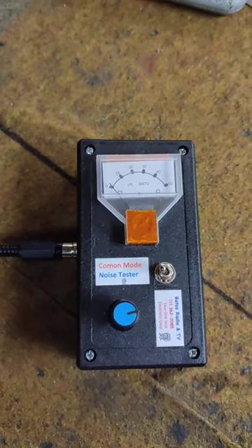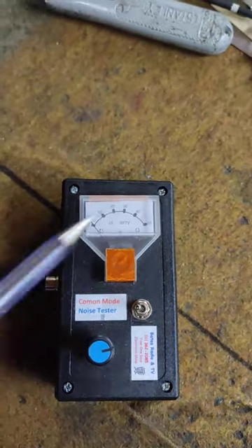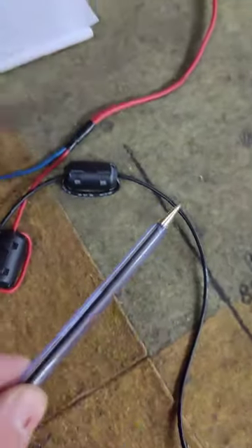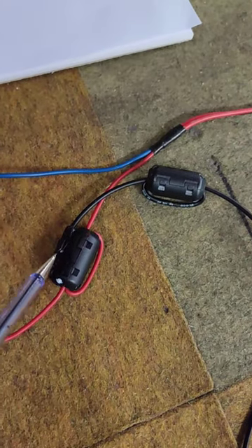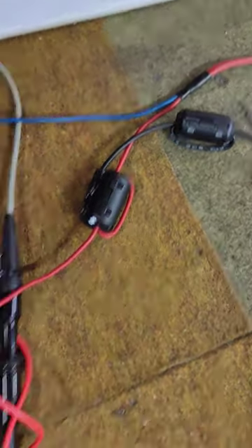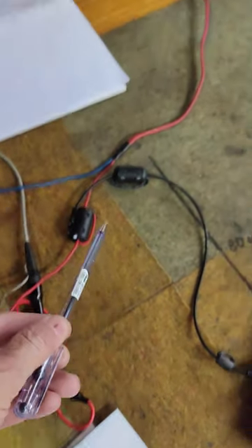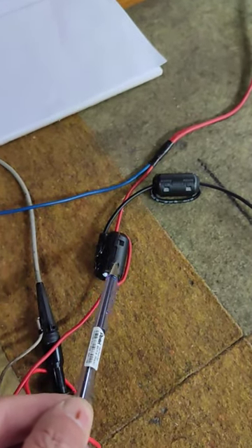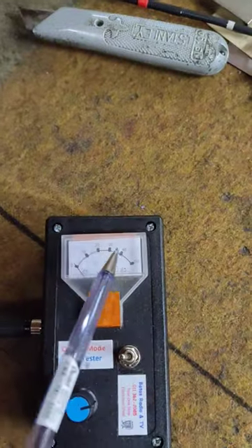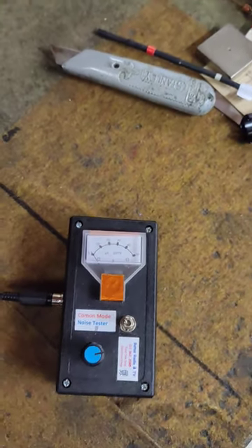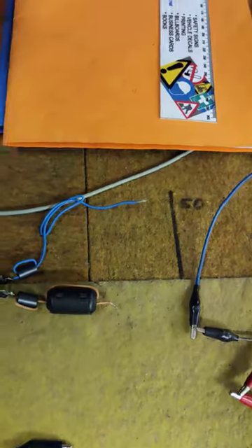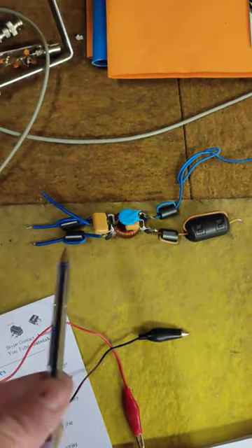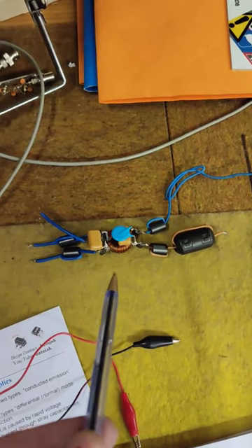tester, which is very, very reasonably priced for what it can actually do and measure, with a special test probe, which actually just gets clamped onto my positive wire going into the power supply. And it will pick up the actual common mode noise and display the magnitude on the instrument. And then once we start, of course, I've got the filter over here, which I'm going to use to try to filter the actual noise.